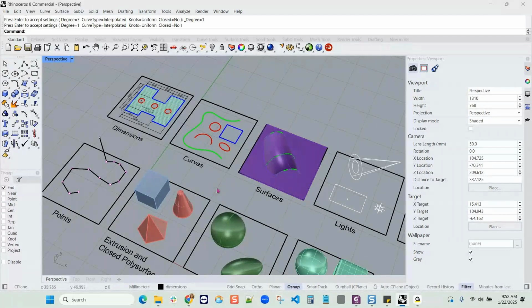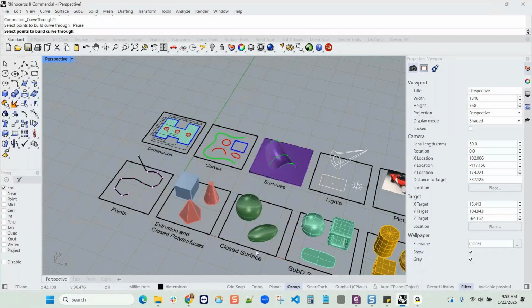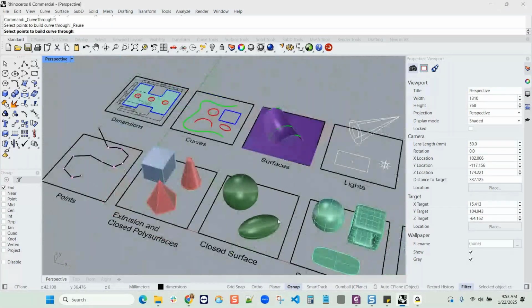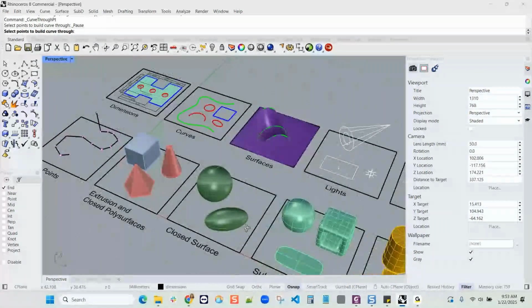You have to have a reason to go higher than that. You maybe would go to degree 7 if you had a reason, but you don't want to if the lower degree curves are going to be able to reflect the shape of your geometry. The geometry just gets more complex and harder to model smoothly with.